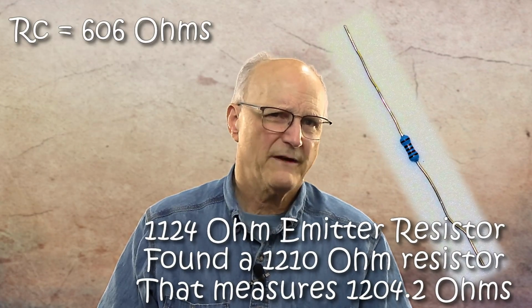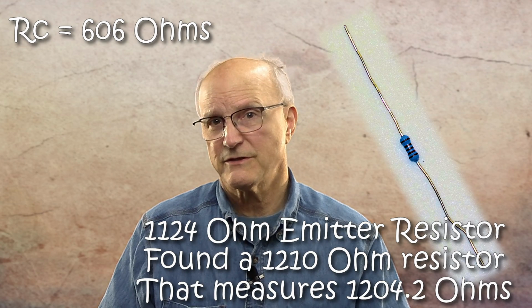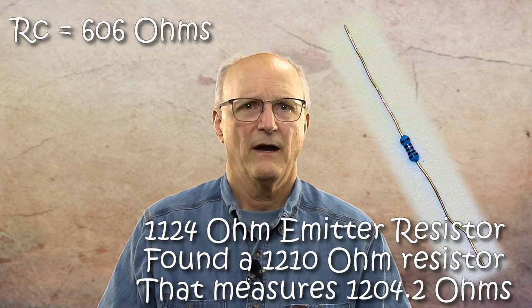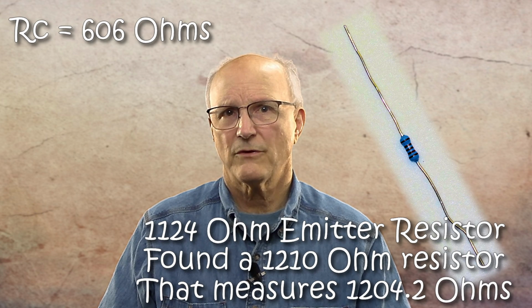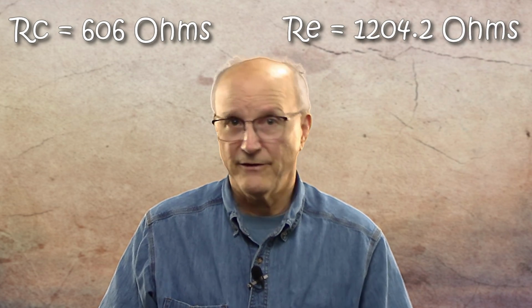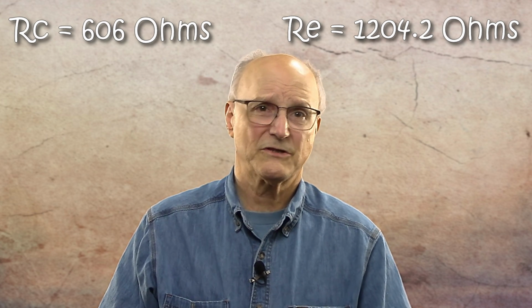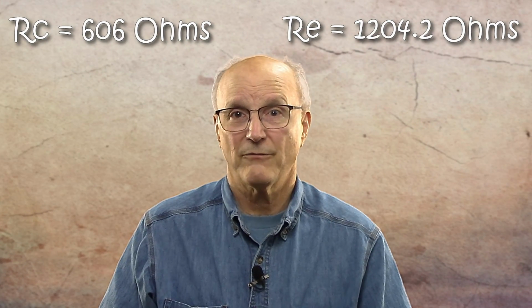And the closest value I found for the 1.124 k ohm emitter resistor is a 1.21 k ohm resistor. I measured its actual value at 1.2042 k ohms. Well, these are not my actual calculated values. And if I'm going to really compare the bench results to the calculated results, I have to reverse engineer my circuit with these actual values.